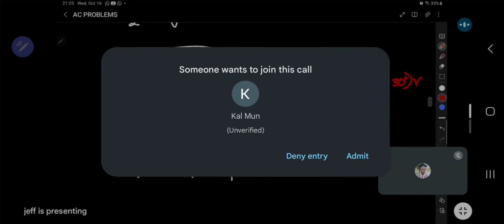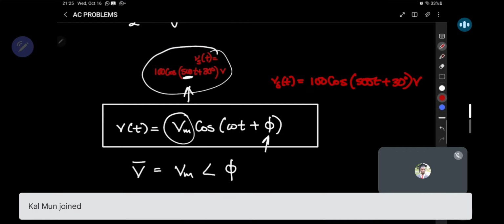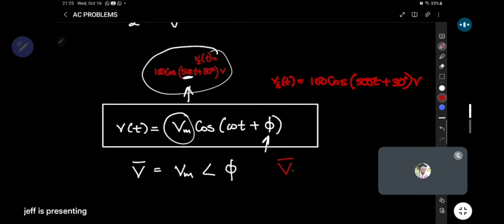So from this, to present it now in phasor form, the corresponding phasor supply voltage, I'll put an S subscript. So the corresponding supply voltage in phasor form would be equal to the peak voltage. Peak is always the coefficient of the cosine expression. So in this case, coefficient of the cosine, we have that 100 there.